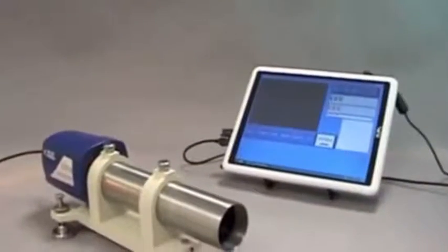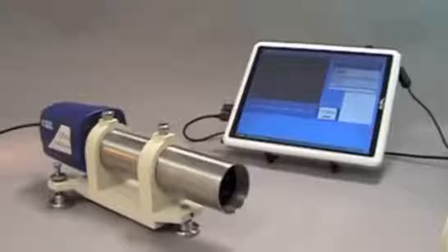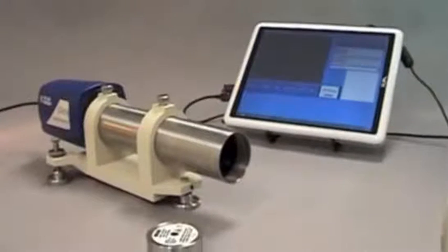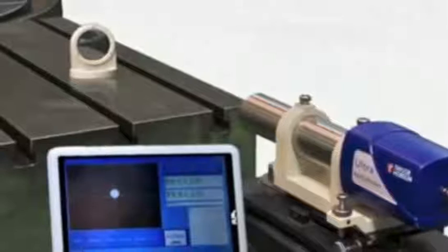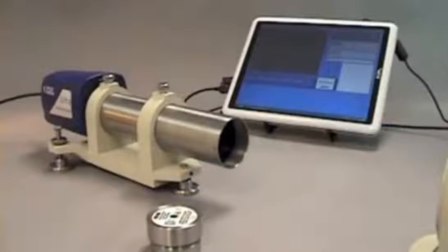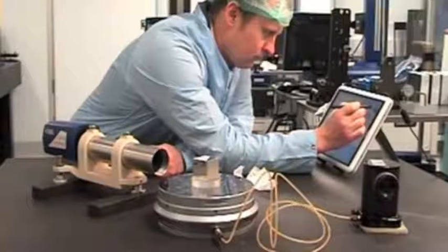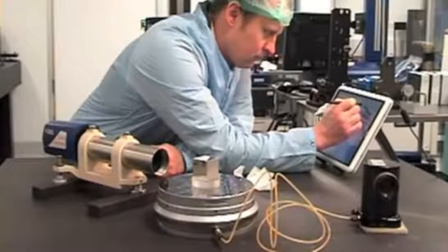For straightness measurement of a machine slideway, I would use the Taylor-Hobson Ultra Autocollimator with its wide range and high accuracy. With the system as standard, you get a laser alignment aid and a tablet PC which acts as the autocollimator's digital display, as well as having the Taylor-Hobson application software packages preloaded.